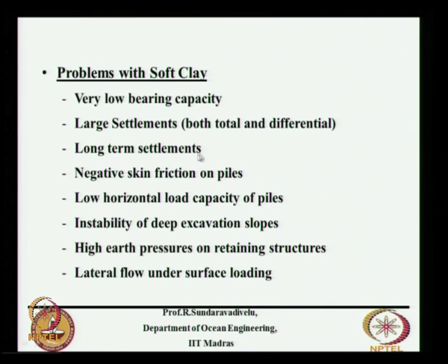This settlement is a long term settlement. The settlement will not be immediate, it will take years, 10 years, 20 years to achieve the settlement. The maximum settlement that we are calculating, about 90% will be reached in about 10 years' time, whereas the balance will take another 10 years.